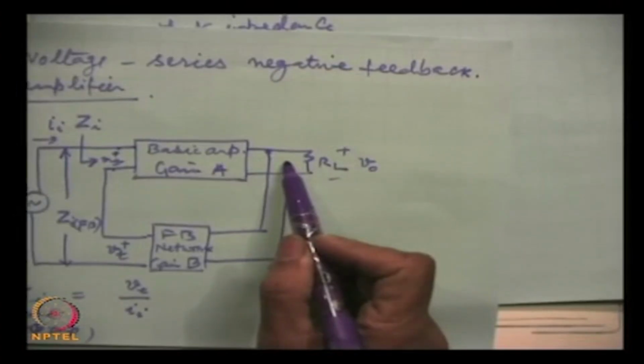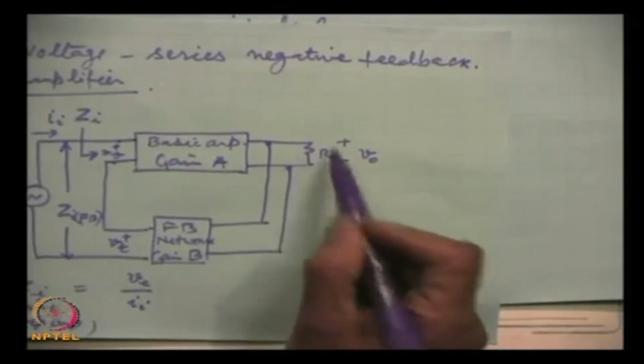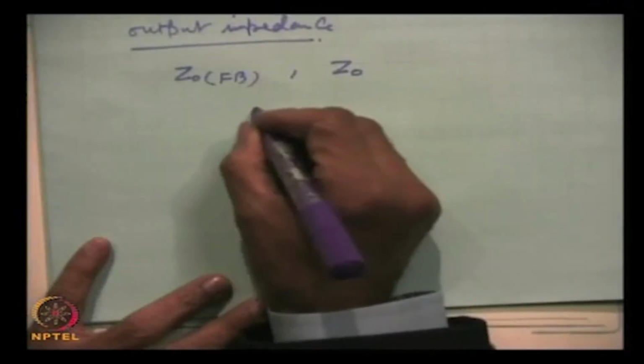Similarly, the rules of the game here are that we have to find out the output impedance here, and this can be done. The first thing which we will have to do is remove this load resistance. Load resistance is not included. This is the general principle of the analysis, that when output impedance is to be taken, take out that resistance and connect a voltage source Vx. So, when we do that, we will observe the corresponding current Ix.